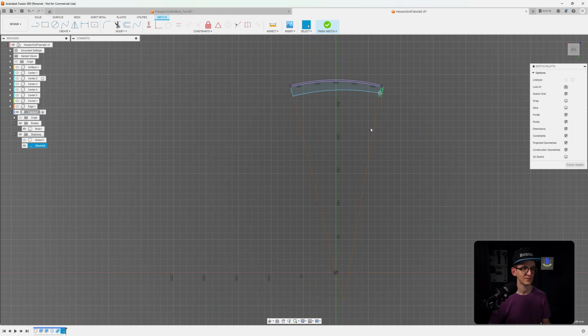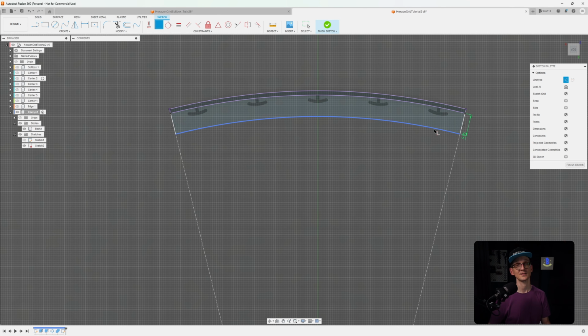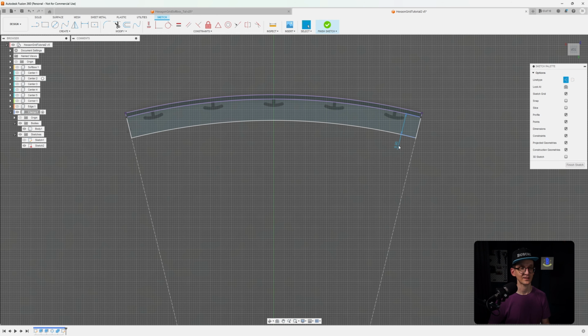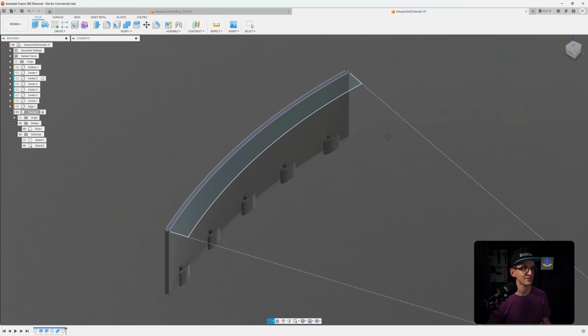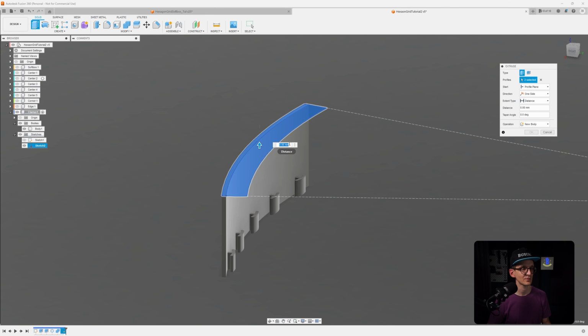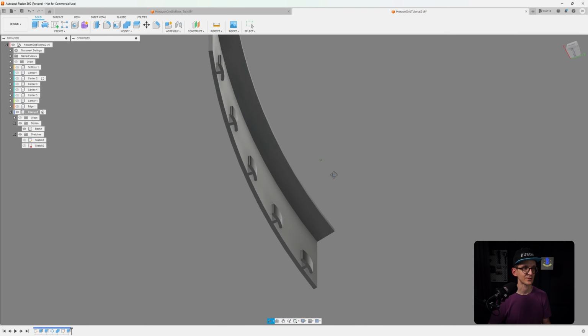Huh? Okay. It's not sitting at the corner piece. Now it is. And it is turning white, which is awesome. So, and that's exactly what we expected as well, because the geometry should be now defined with that, and we're good. So we can step out of the sketch, and as a last final step, we extrude those two together with, for example, 2 millimeters, and we have our clamp.